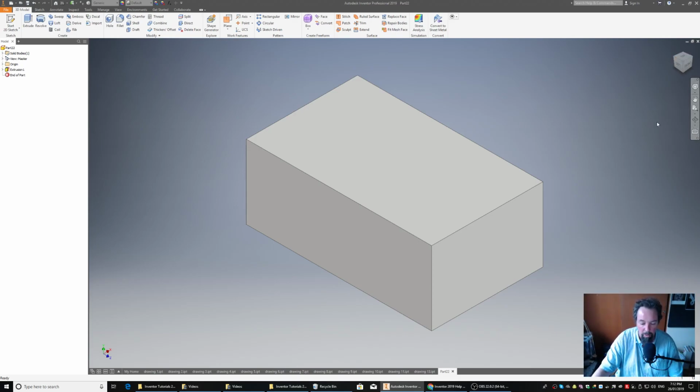So in this case, I'm going to draw the cutouts on the ends here. Actually, I'm going to do the cutouts from the top, and then I'm going to do the side profile on what's left. So I'm going to do 2 rectangles, one on this side, one on there, and then I'll do a side profile. So here we go. Going to start a sketch on the top face.